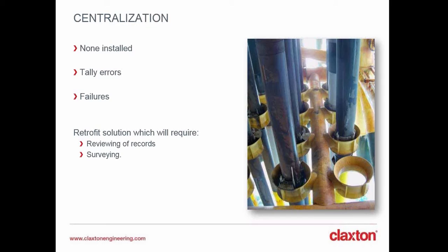And those conductors do need the lateral support to be able to minimize fatigue. It's also possible that there were errors in the tally when the original conductors were run, which means that the principal centralizers are not located within the guide, which could be one of the reasons why they're no longer within the guide.